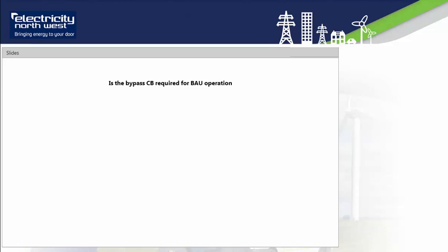Why do customers need to wait 10 minutes before turning back on? What we needed to do under a fault condition was reconfigure the network through an automatic restoration system, then remote control switching. So we needed to make sure that the fault on the network was removed before the customer contributing the fault would come back on supply. So that was why the 10-minute constraint was there, for us to be able to reconfigure the network to reduce the fault level.